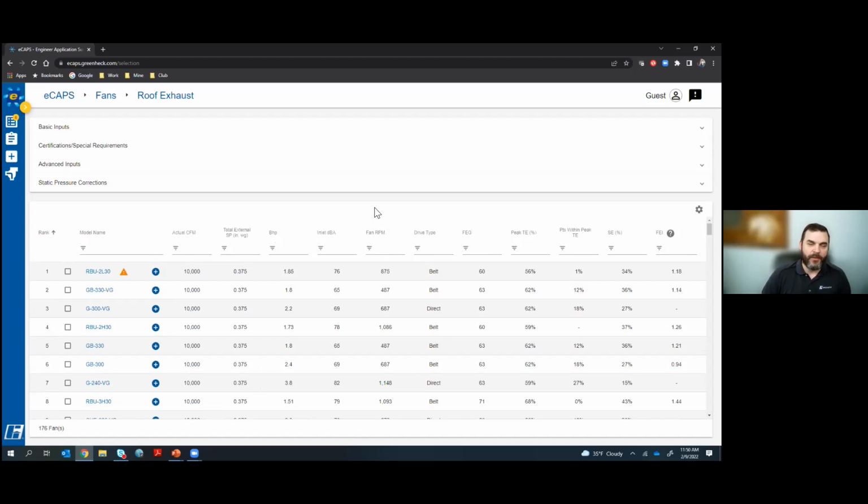This is one of those scenarios where as requirements start dictating minimum FEIs, like the Department of Energy has pushed its way down and it's been adopted into our local areas, well, yeah, then you definitely will toe the line and make your selections and put that right on the schedule. Until then, in my mind, and I have to kind of say this is a ROG or a rule of Greg, I use FEIs to make a good selection when I'm looking within fans.